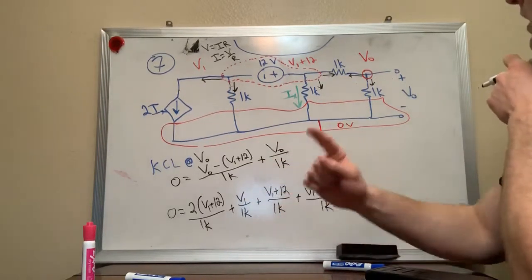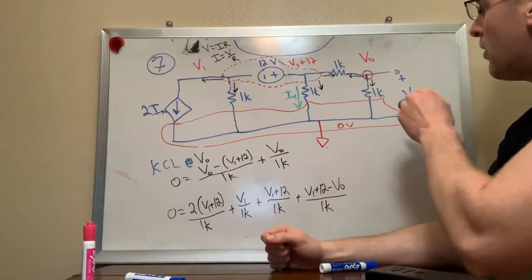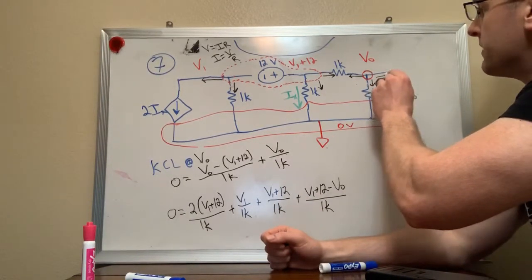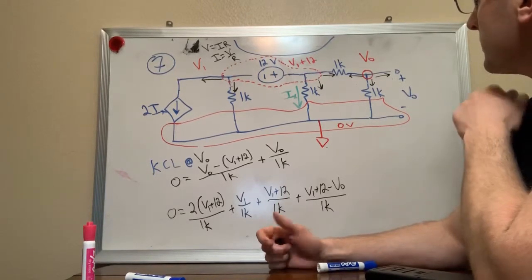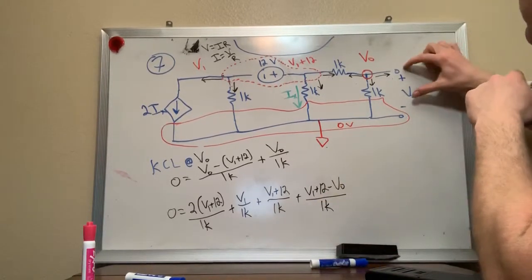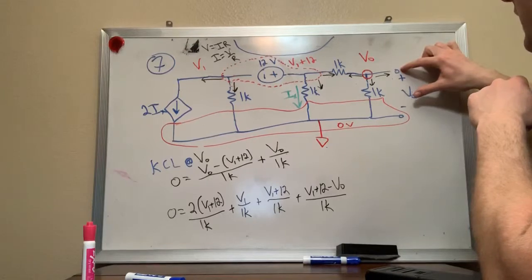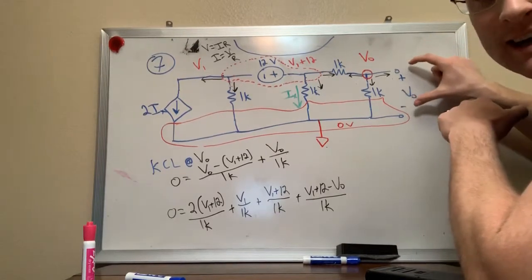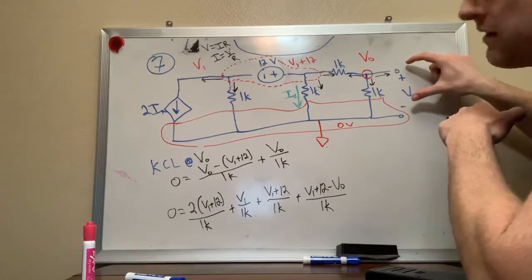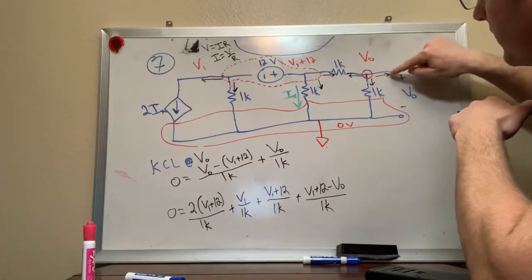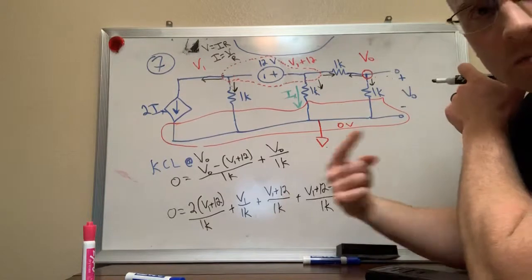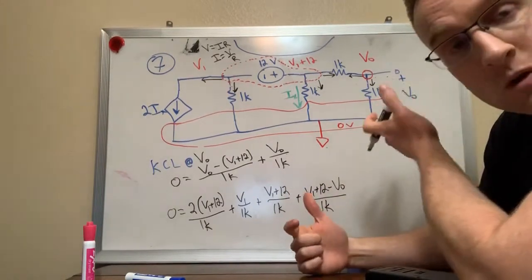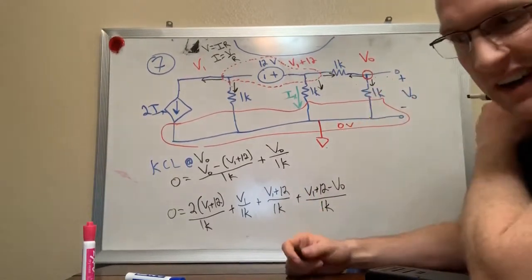All right, real quick, why did I not draw a current going to the right? It's not a complete loop. It's not a complete loop, right? So even though this is an output, until there's a load connected here, there's no current. There's no current going this way, right? This is just a floating piece of copper. It's just hanging there, and there's not going to be actual current flow. There's voltage there, but there's no current.